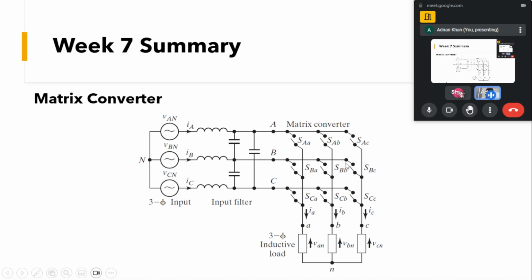If we turn on, let us say, two switches, this switch and this switch, you can see we will be shorting our source. Also, if we turn off all the devices, we'll be opening our load, which will be some inductive load at the output. We have to keep in mind we cannot interrupt the inductive load at any instant.